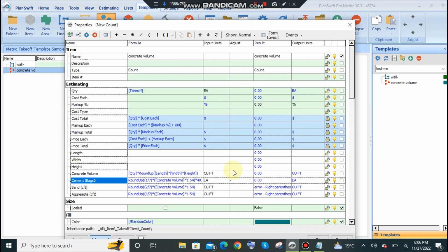Now let's select their unit as well. Shuttering will be in square feet, and this should also be in square feet actually. And for diameter, what will be unit? Diameter unit will be in feet. And for height, unit also will be in feet. For width of column, unit will also be in feet. For length, same unit.